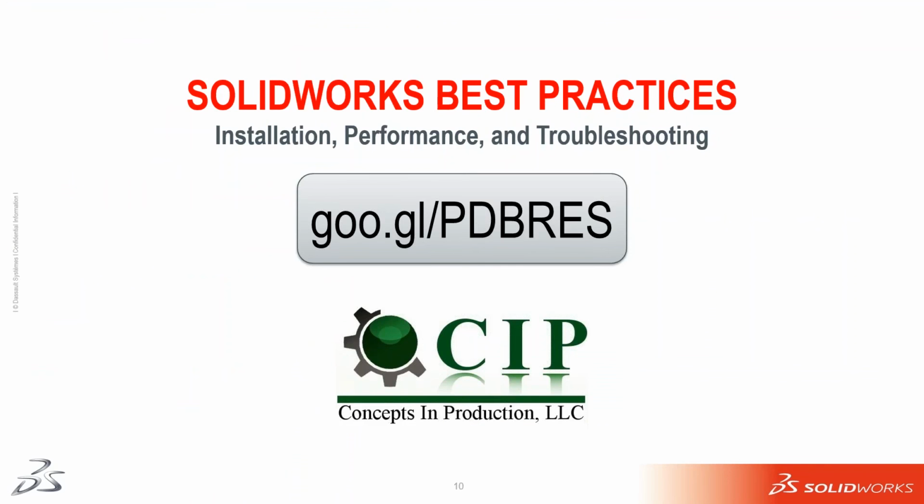So that's SOLIDWORKS best practices, walking through looking at some tips for installations. Make sure you do disable your antivirus, run as admin. Performance issues, working with your hardware and using the tools that are built into the software to make sure you're performing up to par. And some troubleshooting help using the SOLIDWORKS RX tool and those tools we have available in the customer portal.